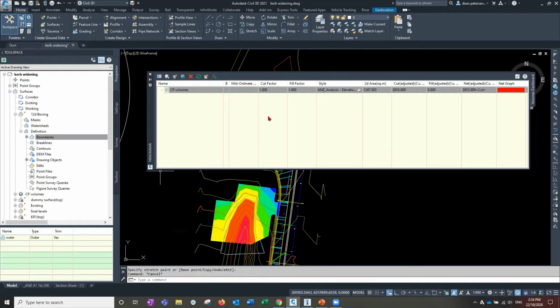All right, so having generated this, we highlight that in lines, it turns blue, and there is a fourth icon here that says add a bounded volume. So it's bounded by the polyline. So if we pick that and then follow the command line, select the bounding object, which is the closed polyline, there's a little plus appears here. If you click that, you'll see straight away that the volume within that area is now being reported.